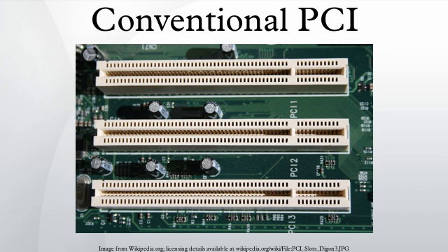PCI Address Spaces. PCI has 3 address spaces: memory, I/O address, and configuration. Memory addresses are 32 bits in size, support caching and can be burst transactions. I/O addresses offer compatibility with the Intel x86 architecture's I/O port address space. Although the PCI bus specification allows burst transactions in any address space, most devices only support it for memory addresses and not I/O. Finally, PCI Configuration Space provides access to 256 bytes of special configuration registers per PCI device.